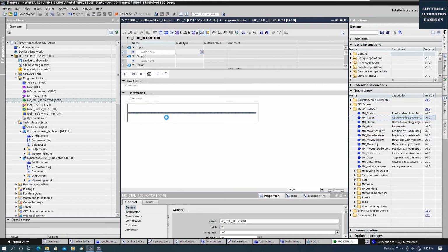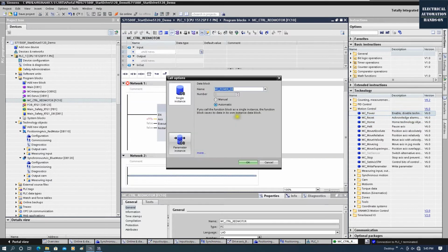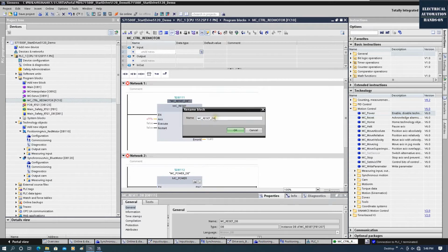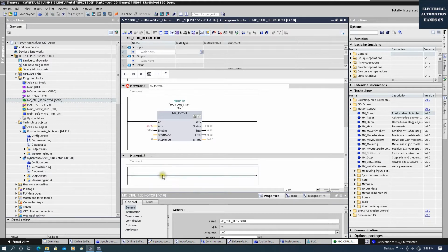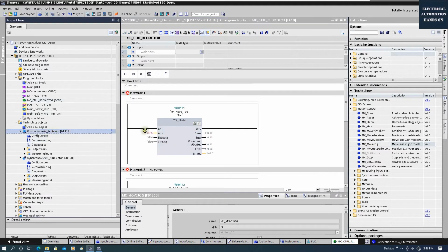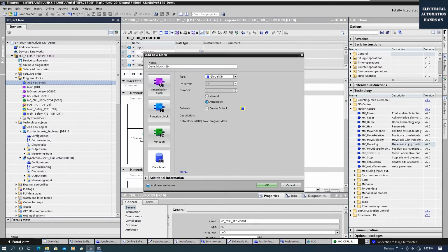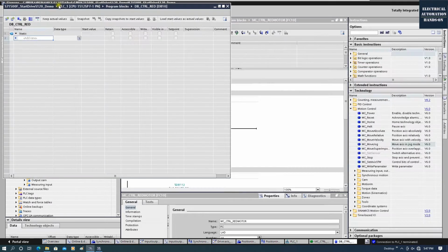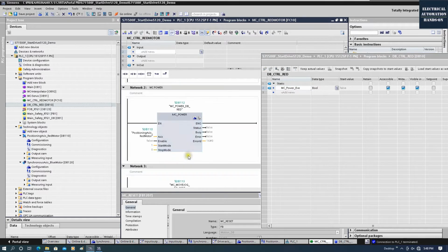Before we configure the safety function on the drive side, from the PLC side you can program MC Reset, MC Power, and MC Velocity, so we can enable the drive and set the velocity. Then we can test the safety function. For example, while the motor is running, if we press the E-stop, the drive stop state will show differently depending on whether it runs STO or SS1. So for testing purposes, I will quickly program MC Reset, MC Power, and MC Velocity.